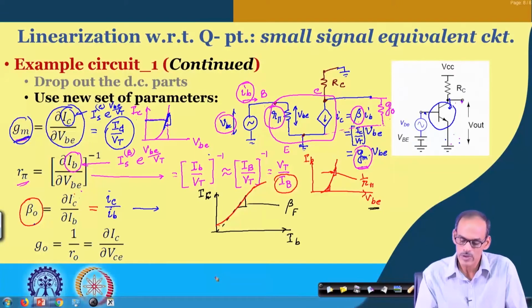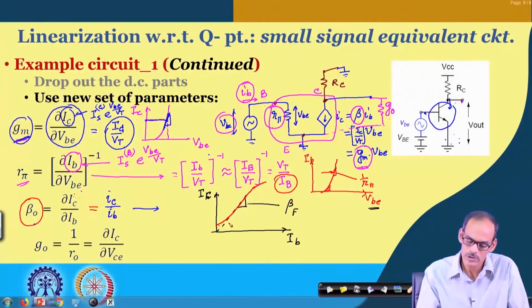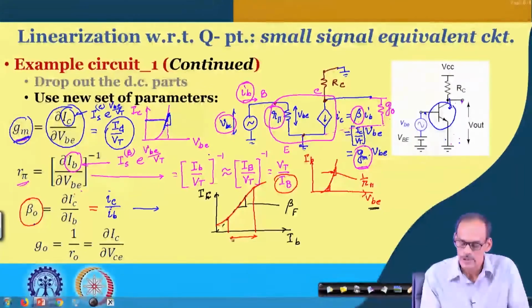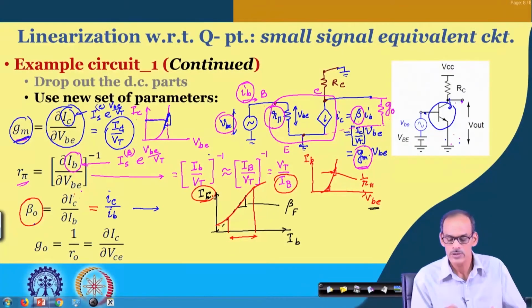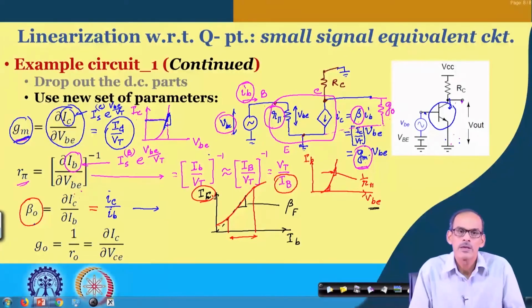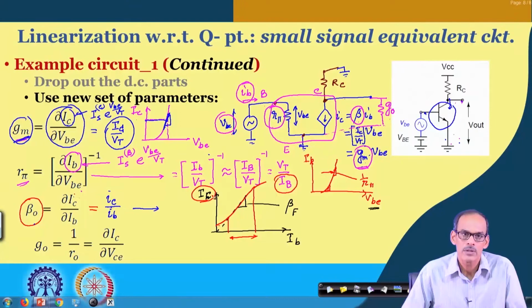I will not go into the details of the sources of those nonlinear parts, but as long as you keep the transistor within a certain range, say a collector current from a few hundreds of microampere to maybe 10 milliampere for a normal transistor, the slope is fairly constant.